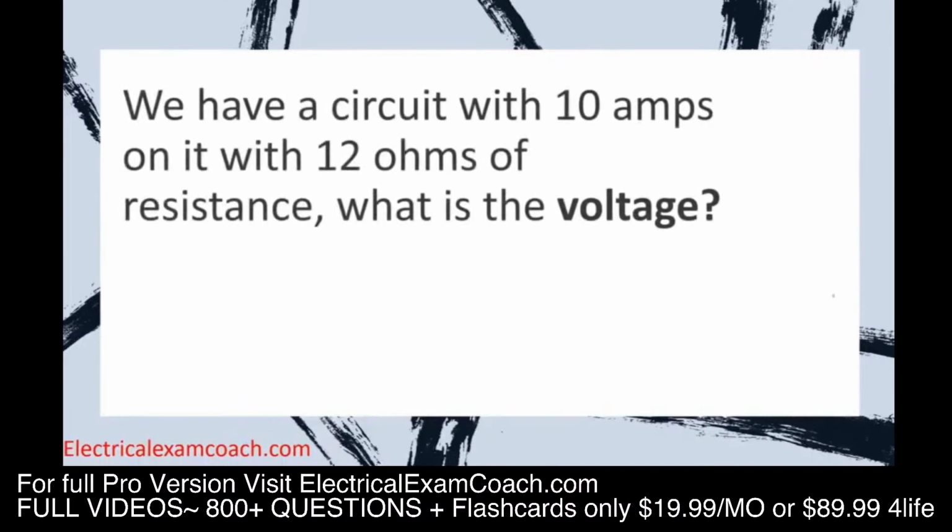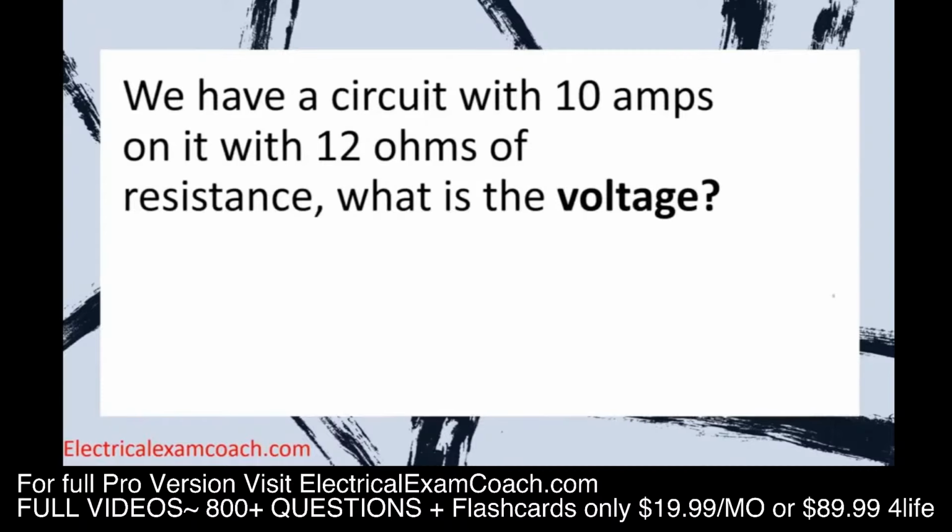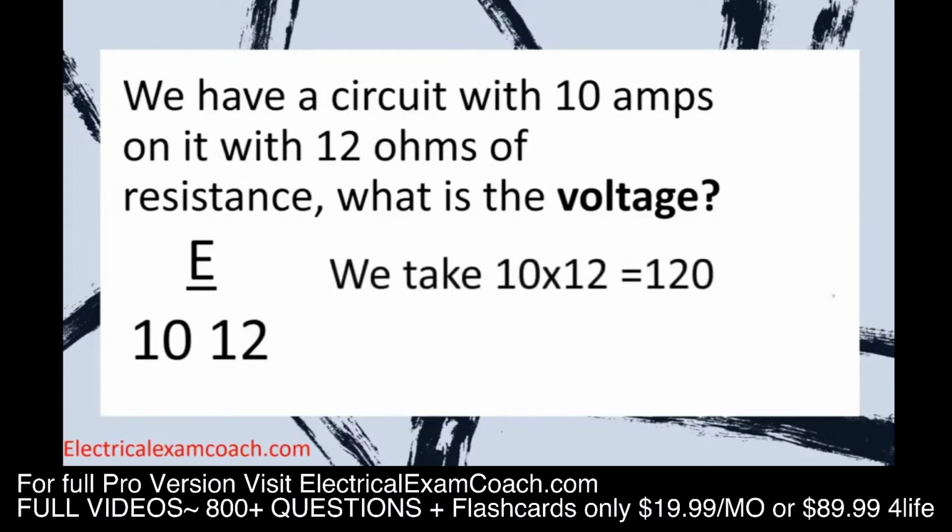Finally, we have a circuit with 10 amps on it and 12 ohms of resistance. What is the voltage? Well, we plug in what we do know. In this case, we're solving for E, and we know that we have 10 amps and 12 ohms. Now all we have to do is follow our Ohm's law pyramid and multiply this out. We take 10 multiplied by 12 equals 120. So E equals 120. Great job.